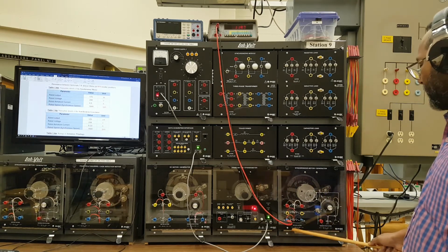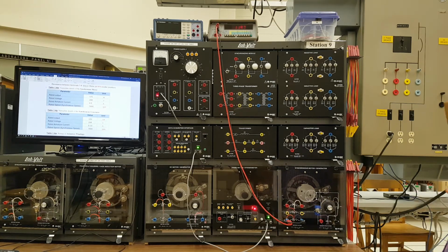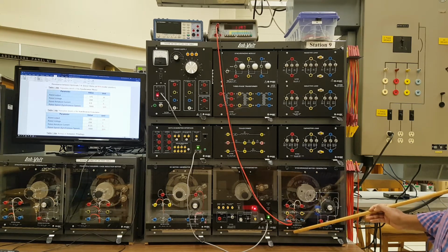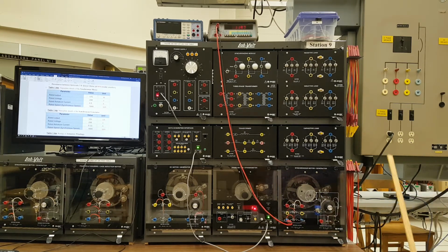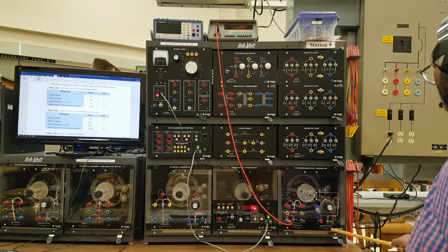In order to produce this much power, 175 watts, I think maybe because the power rating is 120 VA, if you convert it, with a maximum power factor of 1, into active power it's 120 watts, and then this is 175 watts. That means as a motor it is giving more mechanical power, so that's why it's taking 0.8 amperes instead of 0.33.